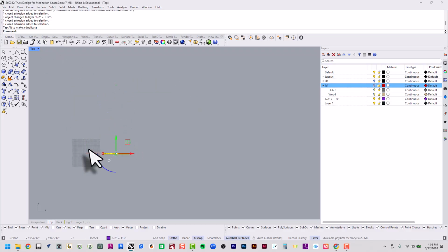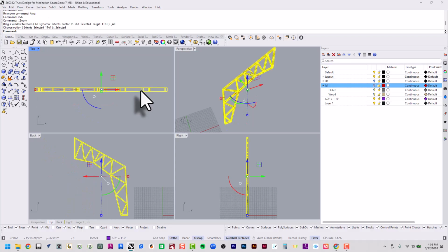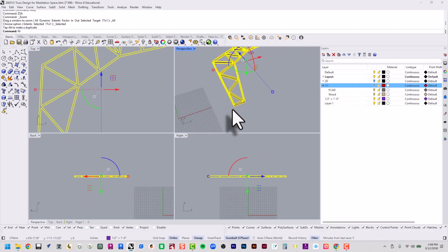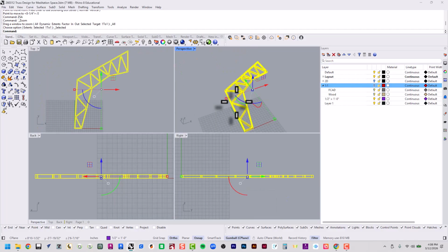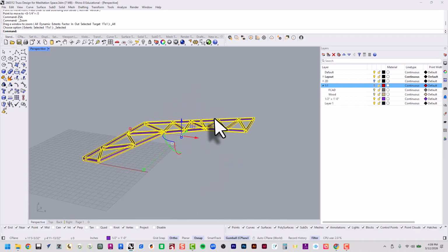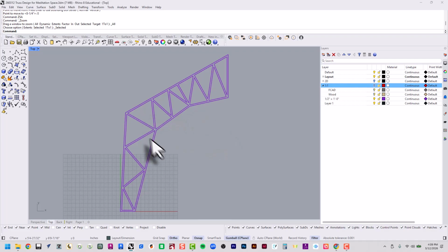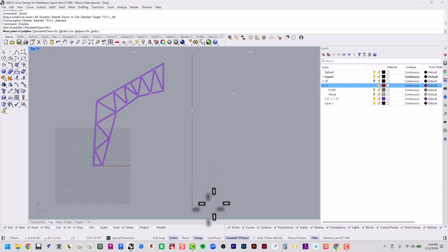For 3D printing, I like to lay this down in such a way where I can view it easily in top view, because when I go to import this, it'll come in relative. So let's move this to the origin, just like that, so it's laying down on the ground. And now I need to perform a magical spell to bring it down to the correct size. The way I like to scale in Rhino, and this might be a little old-fashioned or weird or different, but this is the way I like to do it.